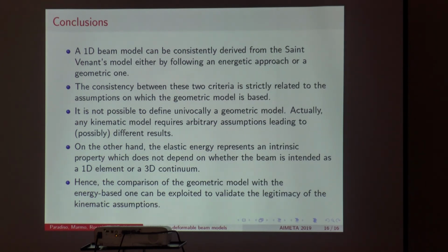In this sense, it is just a representation of the constitutive behavior of the solid. It is the same as saying that the normal force in the Saint-Venant theory is applied at the center of the section. In this case, the normal force is uncoupled from the bending moment.